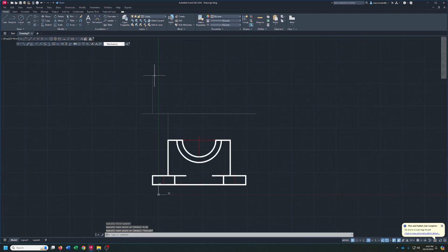And that's my start spot. So I'm going to go ahead and get object line, pick, boom. Now I'm going to line it with this and bring it straight up. And then I'm going to come forward 3. Then I'm going to come over 2.5. And then that's where I'm going to put my radius circle. 1 there. Now I can trim off this like so.